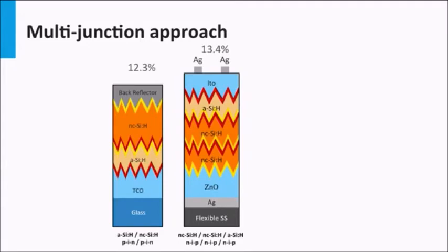Another aspect of thin film silicon solar cells is the current matching between the various solar cells. Textured surfaces are being used to scatter light into the various junctions to enhance the absorption path length, which allows the use of thinner absorber layers. This becomes more important for the bottom cell, as this nanocrystalline silicon film is the thickest layer in the device and it has to absorb the most reddish part of the spectrum.